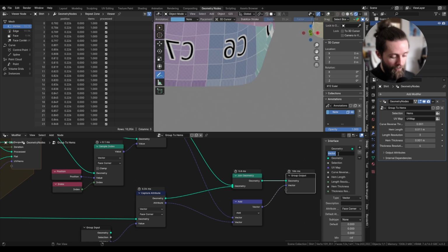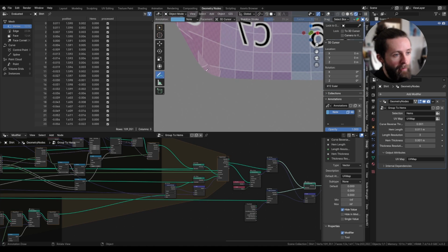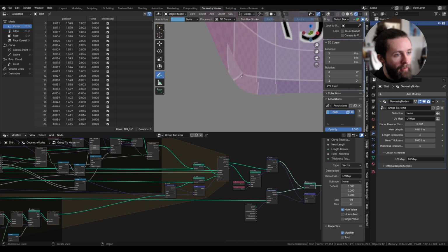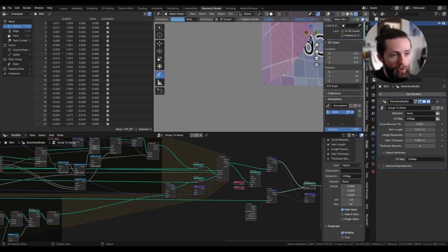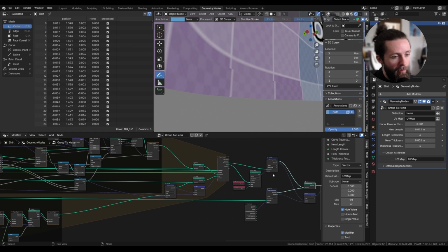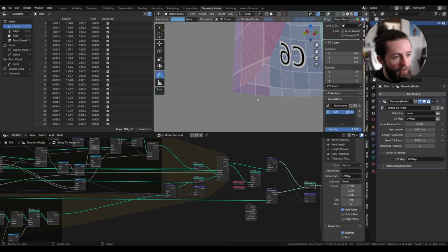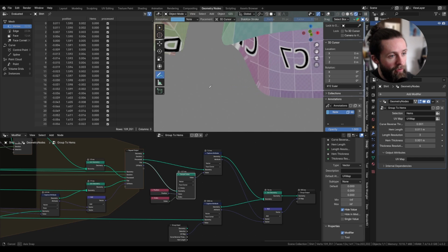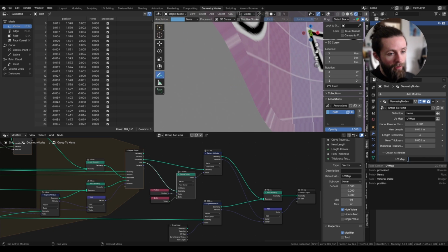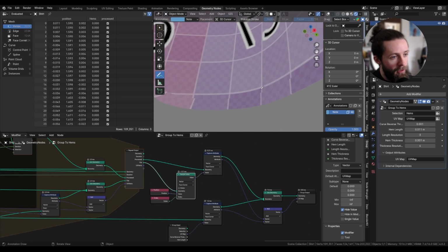We can rename it UV map and with the default attribute of UV map. And now the UV map is properly set up over our hem, and it is really the continuation of the original UV map, which is looking really nice. So this is how it was looking before, with just really stretched UVs, and now we get proper continuous UVs.